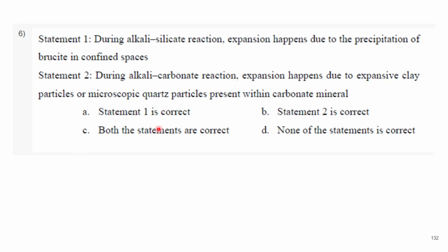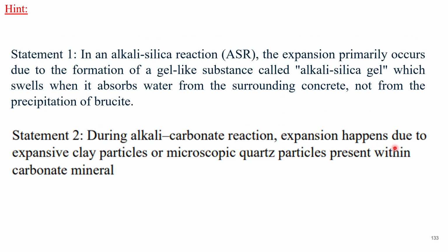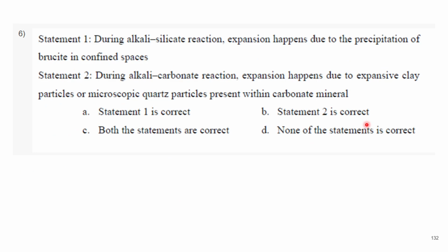So one is not correct, but the second is correct. Alkali carbonate reaction expansion happens due to expansive clay particles or microscopic quartz particles present within carbonate mineral. So two is correct. So B, statement 2 is correct, is the right option. So B, statement 2 is correct.